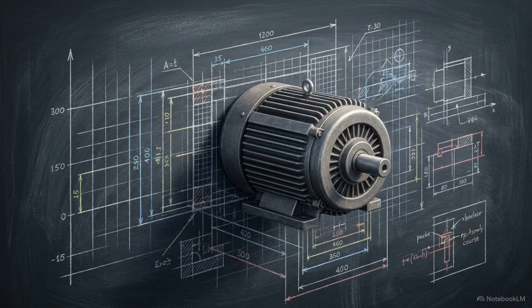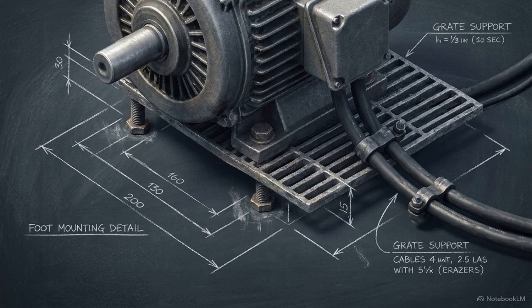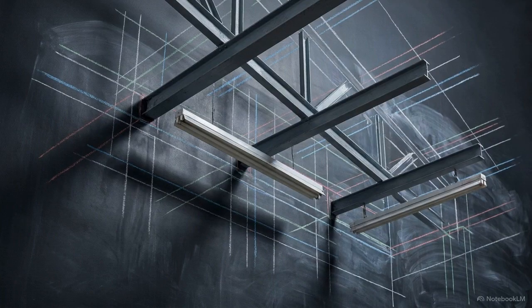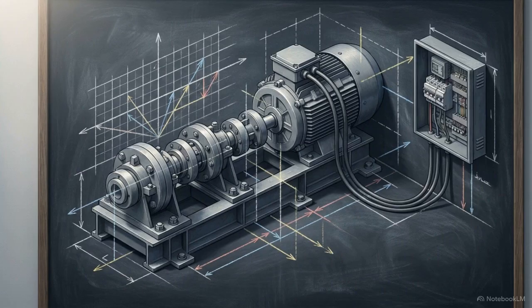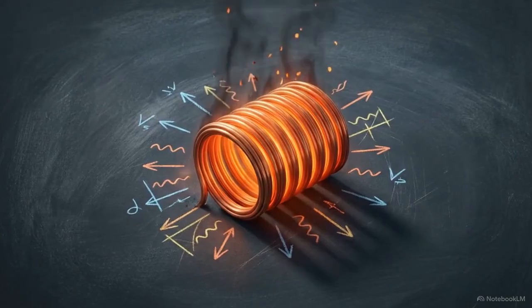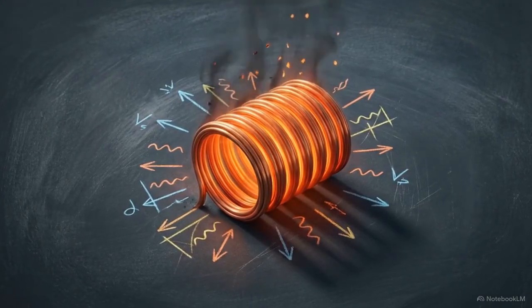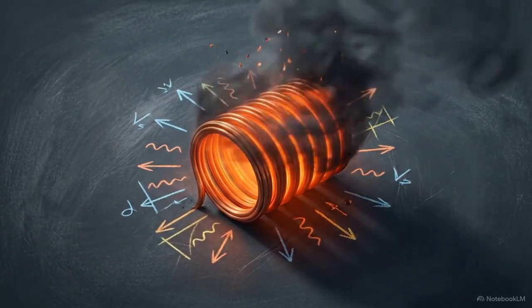To know exactly how a heavy industrial induction motor will perform at full capacity, you could bolt it to a test bench and load it to its absolute physical limits. But in the real world of engineering, that approach has a hard ceiling. Pushing massive motors through their complete operational envelope on a dynamometer takes enormous amounts of power. It is expensive, highly impractical, and severely risks melting the very copper windings you are trying to measure.